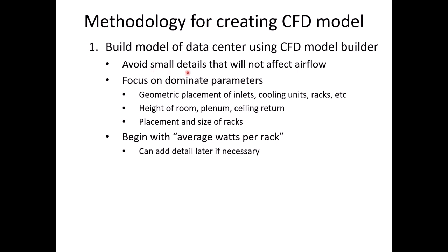One of the things that I run into with new users is they want to put everything in it, and you can learn a lot with a fairly coarse model about what's going on in the room. You don't have to put every little tiny thing in the model. If later on you want to add details to see if they make a difference in the results, it's easy to do. So focus on the big stuff.